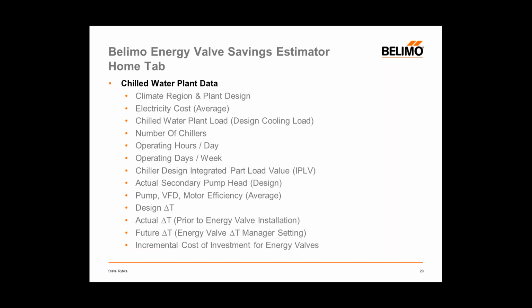And then we'll also need the incremental cost of investment for installing energy valves as opposed to installing pressure-dependent valves and circuit setters. This may seem like a lot of information. However, the majority of it is going to be available from manufacturer specifications as well as design or as-built drawings or data.